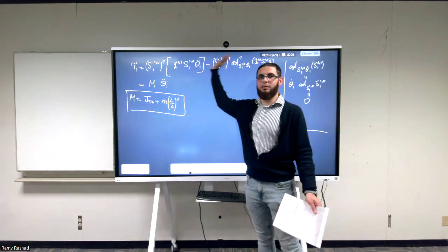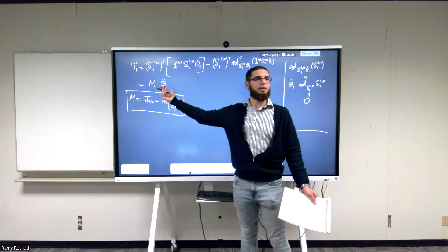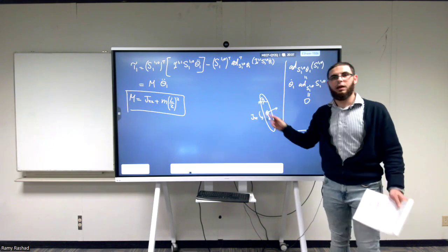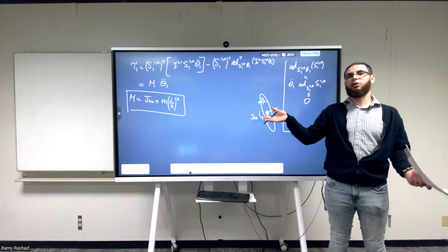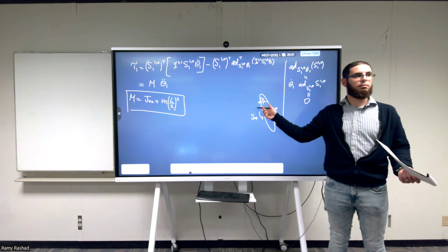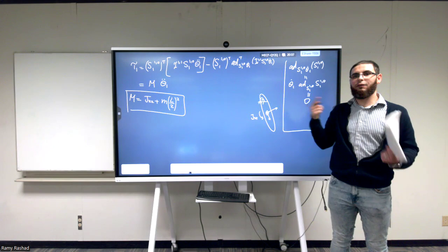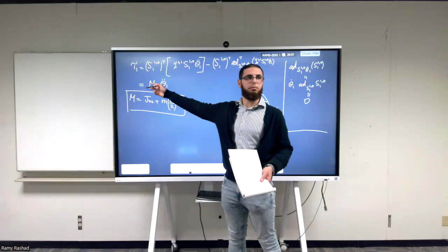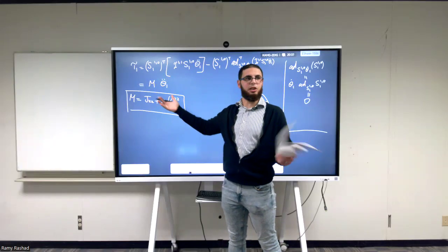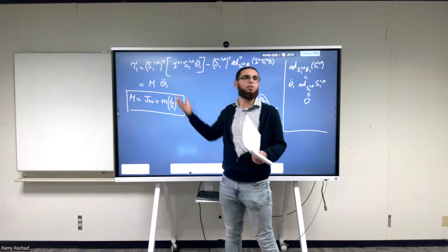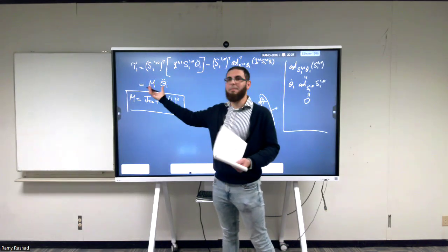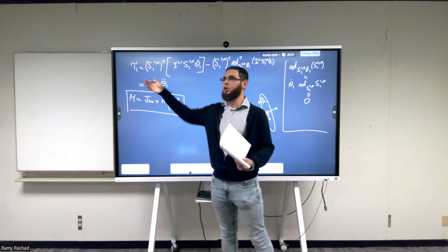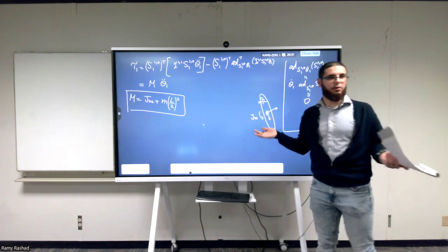So in the end, after all of these simplifications, this is the reduced dynamics. How many degrees of freedom does this system have? Only 1 degree of freedom, right? I had one rigid body in the start, which was 6 degrees of freedom. I constrained 5 of them by the joint. I'm left only with 1. So I have only a scalar equation that says theta double dot multiplied by some inertia. This is a rotational inertia. I write it here as M because in general this is a mass matrix. You're going to see why we call it a mass matrix next time, inshallah. So this is a mass matrix, or in this case, just a scalar inertia, equal to torque. So torque is equal to inertia multiplied by theta double dot. Nothing fancy, nothing new here. You all know that.